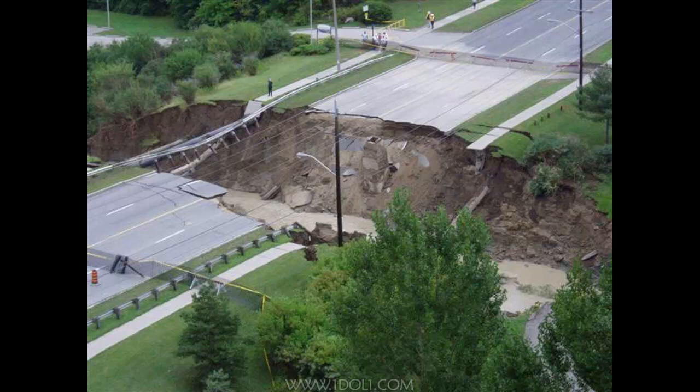I think that probably whoever designed that isn't working as an engineer anymore. Probably. Yeah. I mean, we all make mistakes, but that results in that big of a mistake. I think that this one was probably, unless it was installed wrong, and that's possible. Like if the soil wasn't correctly compacted around the edges of the culvert, then the piping could have occurred more easily than it should have. But without knowing all the facts, just my suspicion is probably the culvert wasn't as large as it needed to be because too much water was accumulating upstream.